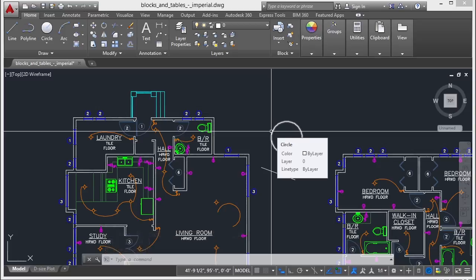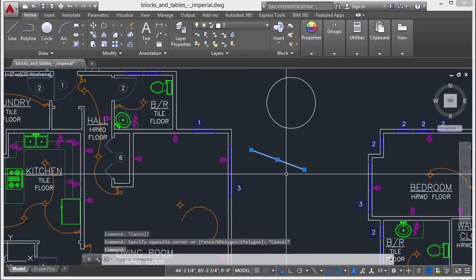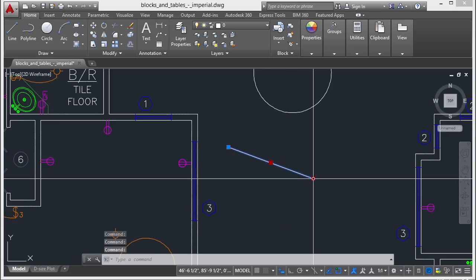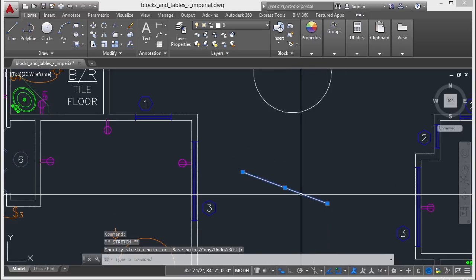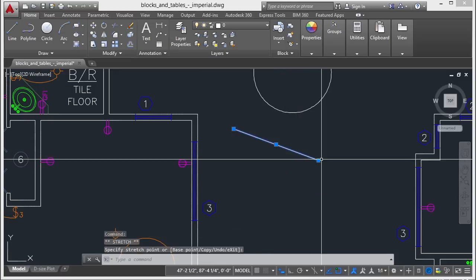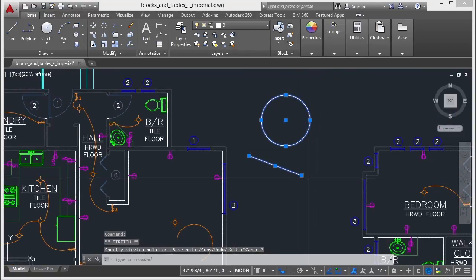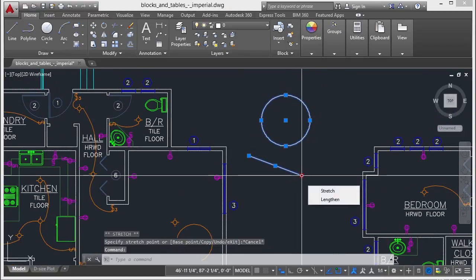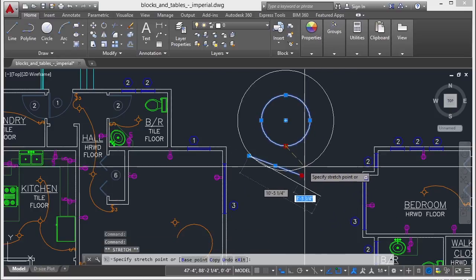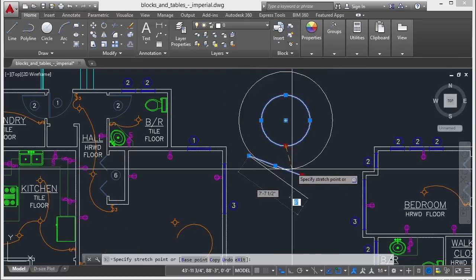Now, you can select multiple grips at a time. So if I select this line, select the midpoint and the endpoint, this becomes a move command. And it's going to keep these relative to each other. It's kind of like still doing just the center point. But if I select another object and I select by holding down Shift, just that one grip, as well as that grip, I'm changing both of them relative to each other. So I'm changing them both according to how I move it.